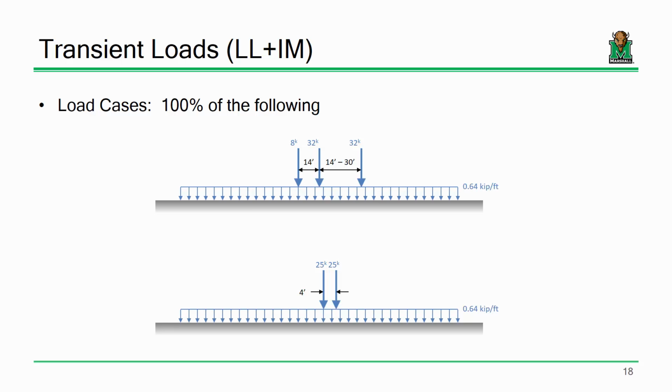So let's envision a scenario. Here's a bridge. I've got a support here, I've got a support here, okay? Now, let's say here's the truck. I can move that truck up and down the bridge, it's transient. It can be wherever. Let's say I'm trying to generate the maximum possible bending moment that I can. I want this truck to produce as much bending moment as possible. Where would I put the truck? Would I put it over here? Maybe in the middle, right? That's going to make it bend as much as possible, right? And that's what that whole theory of influence lines taught you way back when in structural analysis.